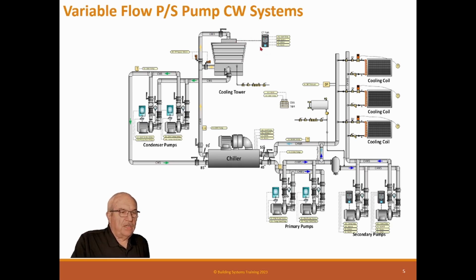The energy saved will pay for itself in less than 18 months on every one I've ever calculated, and I have calculated a lot of them. So I just give up and say every tower should have a VFD. Remember that not only does it save energy, but it also saves gearboxes if it has a gearbox, or it'll save fan belts if it has belts on it. So those are really important to do.